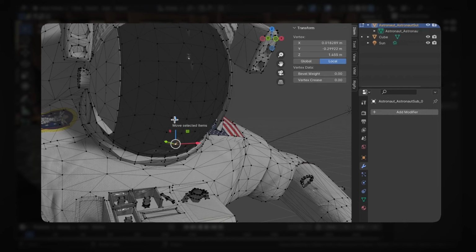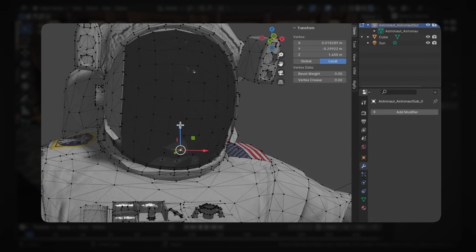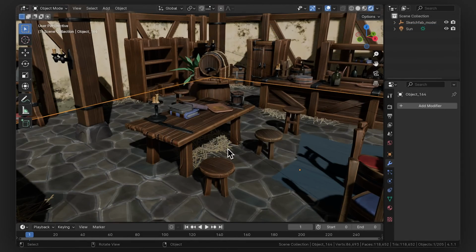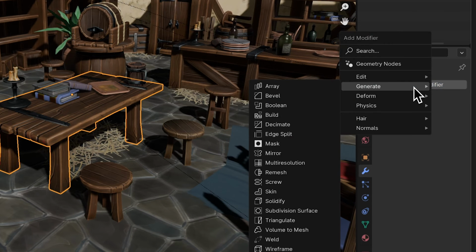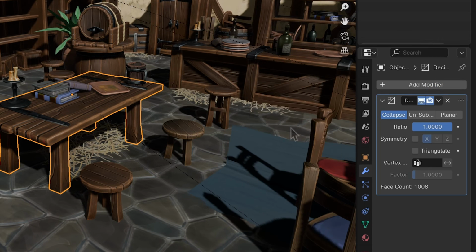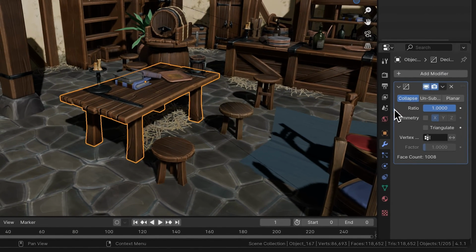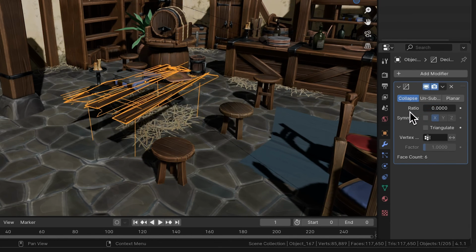Ideally, it's best to rebuild the model geometry through retopology or use a low-poly 3D asset alternative. However, if you do not have the time or the 3D modeling skills necessary to do so, you could quickly solve this by forcefully lowering the object's poly count by applying a decimation modifier. This can be done in the free third-party 3D software Blender or other industry-standard 3D software such as Maya.